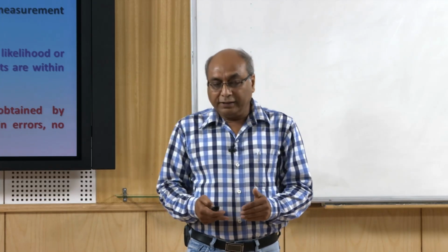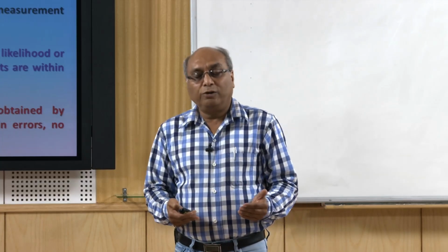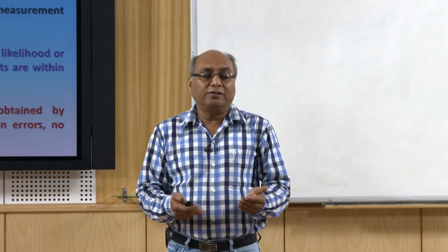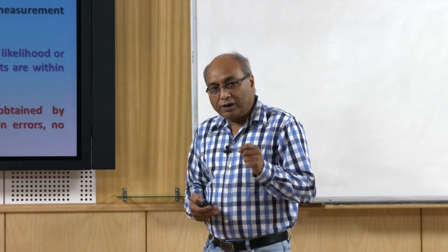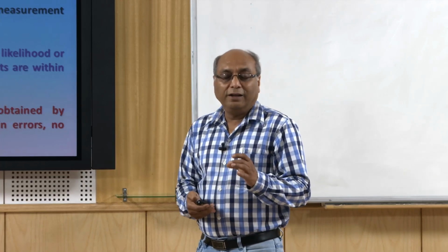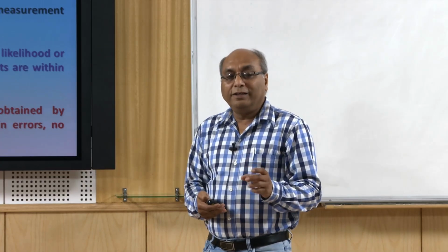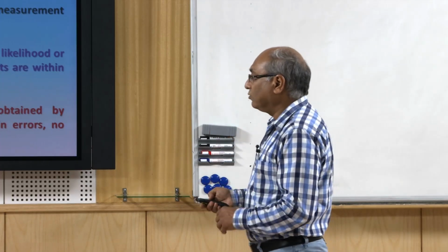But if they mention it, generally in 50,000 scale topographic maps the horizontal errors are somewhere around 30 meters. So the object which you are seeing may in reality be within a 30 meter radius. That means plus or minus 30 meters.